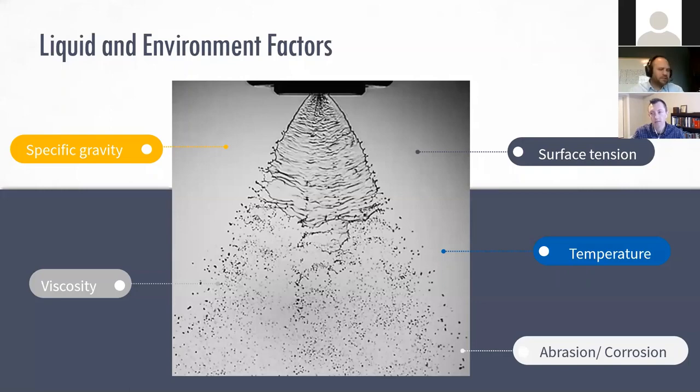Yeah, surface tension is just a little bit different. Typically, we find that the surface tension of a material does not change in a more gradual way like viscosity. And so with surface tension, you might think a material is going to spray and it doesn't for some reason. And sometimes you can point to the surface tension for that. And if you can just increase the pressure a little bit more, you'll find that spray that will not atomize nearly at all will all of a sudden burst into a fine spray based on its surface tension. So, balancing these different parameters is something we do in the lab all the time, and we do our best to identify which rheology characteristic is leading to a poor or underperforming spray, and how to turn the right knobs to find an atomized spray.